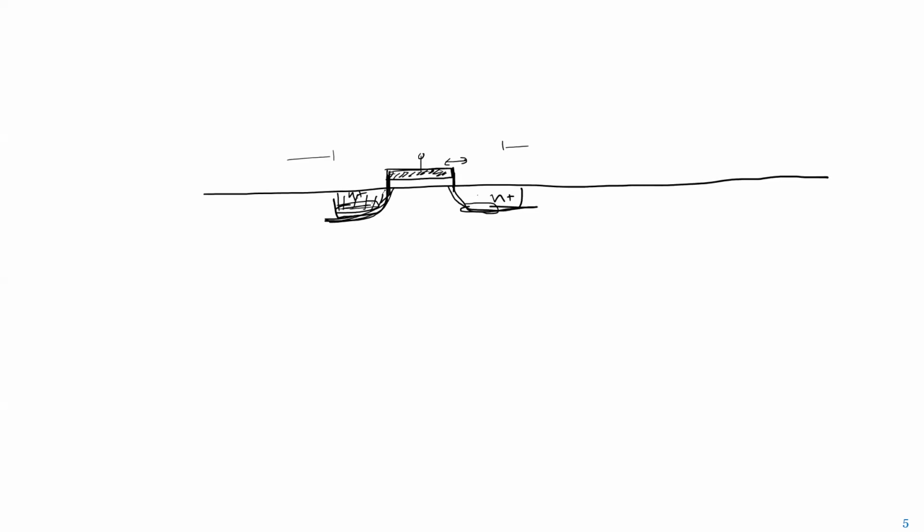Now when they heat it, this heating temperature is very high. Most of the metal, if you put it, will melt away, okay? Polysilicon's melting point is much, much higher. So with poly, even though you have bombarded it, it actually anneals and becomes a good conductor. And then they do something called salicide, where they put a thin layer of metal on top of this after the annealing. So short answer, if you put a metal, it'll melt because they do a heating process after that. Poly doesn't melt. Does that answer your question, Gautam?